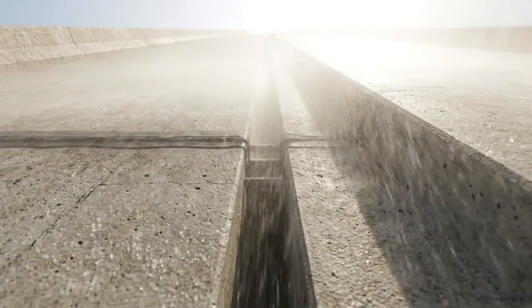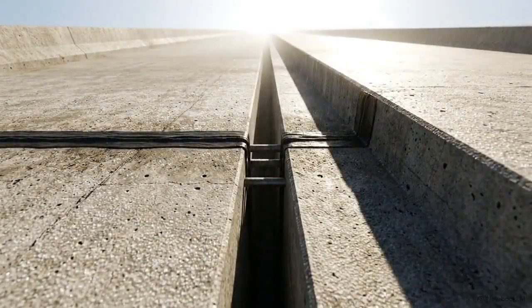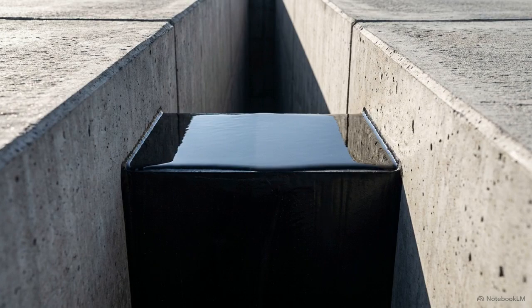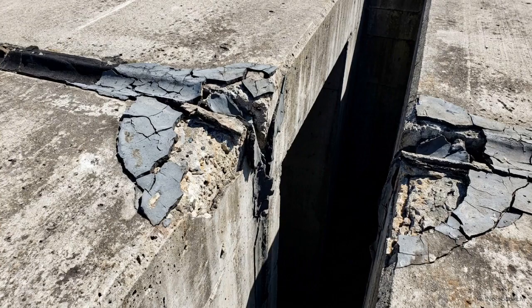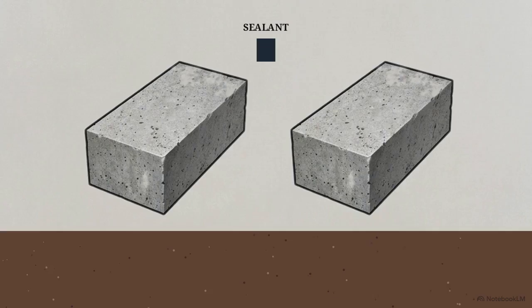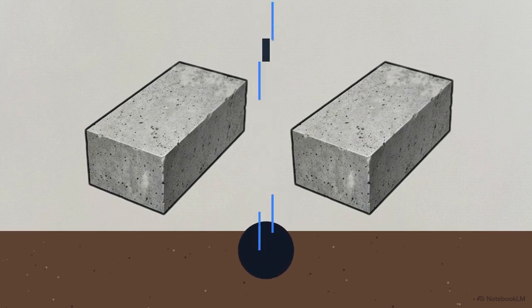Fast forward to the highway's operational lifespan. The slab's physical defense is entirely handed over to the joint sealing compound holding the surface line. The compound's sole job is preventing the ingress of water and foreign matter into the gap, but it degrades relentlessly under heavy traffic and ultraviolet exposure. The first mode of failure is shrinkage. The compound pulls away from the concrete faces, turning the joint into a funnel. Surface water channels directly into the subgrade below, eroding the soil and destroying the foundation's load-bearing capacity.